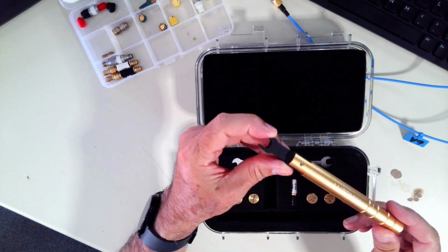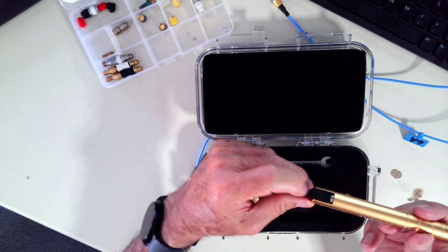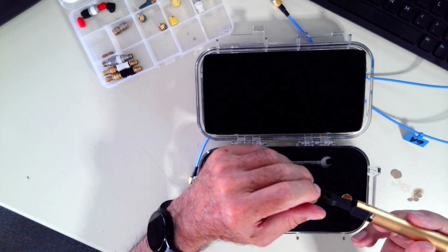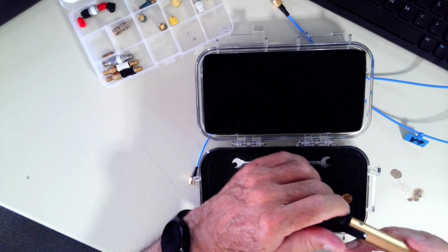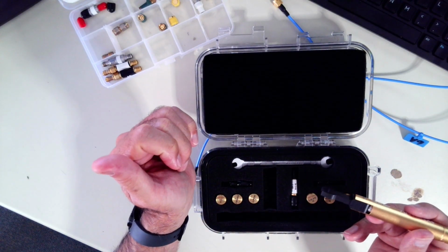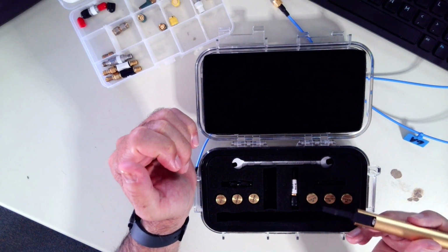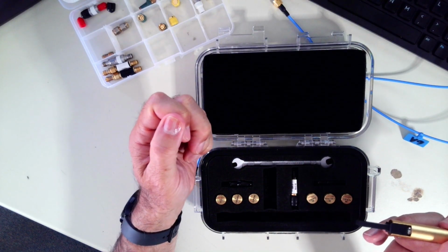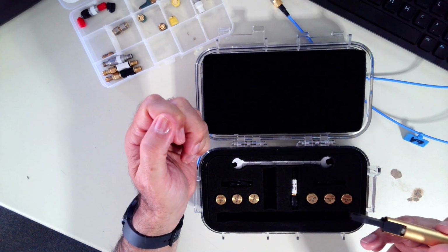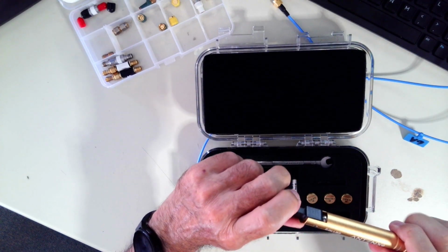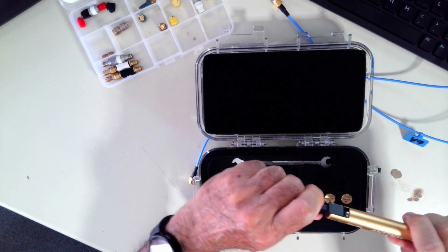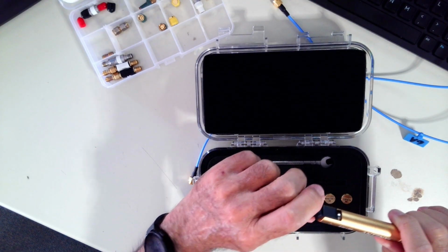This is a 5 inch-pound torque wrench. And this is to be used when you are tightening connectors onto the VNA or to other items so that you do not over tighten them. It is amazing how much, I call it gorilla tight, that students will over tighten these things and then they can't get them off. So you use this, and when you get up to 5 inch-pounds of torque, then the wrench automatically bends and tells you, okay, that's enough.